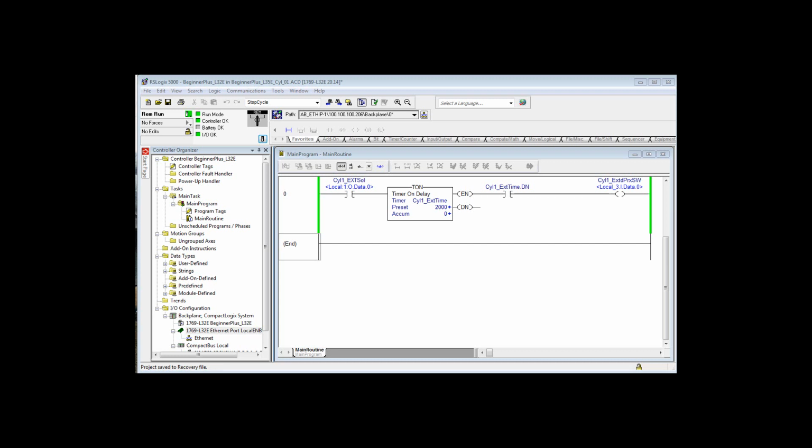Personally, when I work on a process, I, for the most part, get right in their face that I want a sensor on both ends. What they'll do to save a few bucks is only put a sensor on one end of the cylinder. Now, in some cases, 2 sensors won't even fit on the cylinder. I've seen that hundreds of times where the stroke is so short or the space is so limited, you cannot put 2 sensors in there.